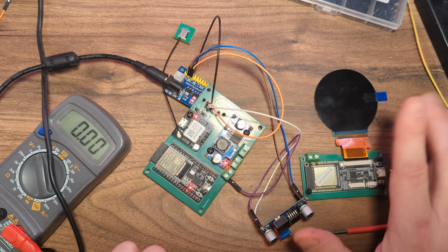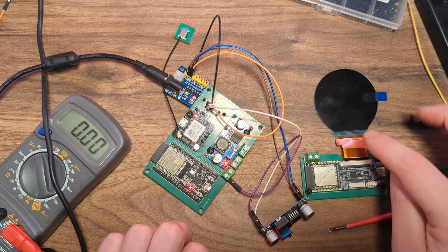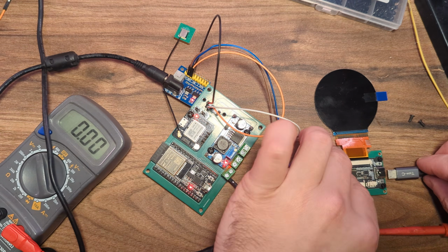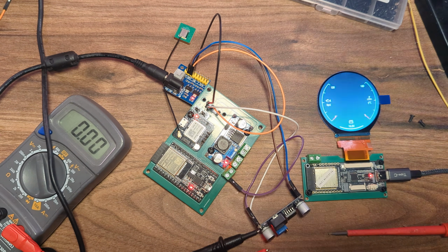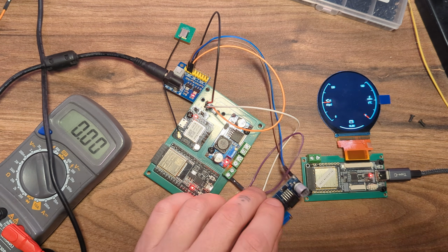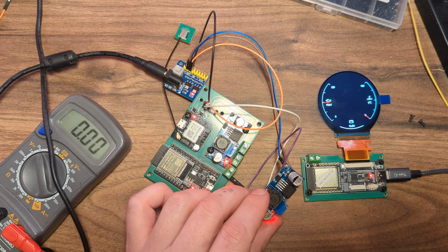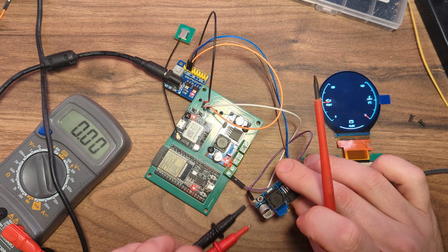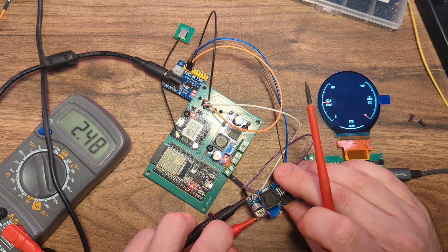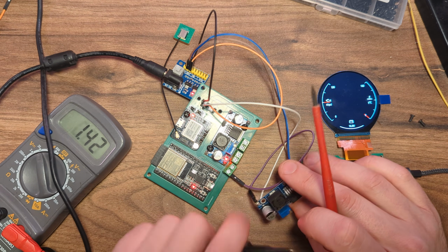So we'd expect it to be in the region of the middle, so like 60 PSI, give or take, maybe a bit over. Let's have a look. 61. So it's kind of in the right ballpark. We expected 60 at 2.5 volts, and it's a little bit higher than that, 2.7.